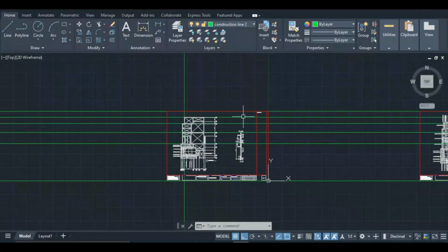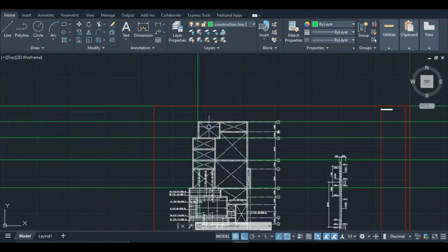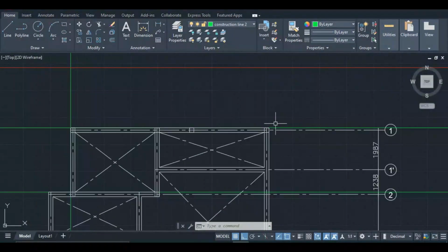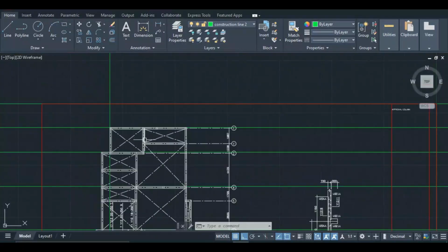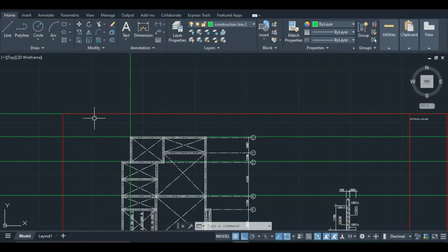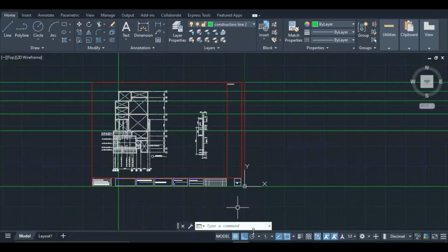So now that's all about construction lines and making sure that your drawings are actually perfectly straight. Now one thing to note is that when you are adding your construction line, you have to make sure that you're on the auto mode, because if you're on the polar mode, the construction line may have a tendency to get at some funny angles, that will make your construction lines not perfectly align with your drawing, even if you have a very straight drawing.